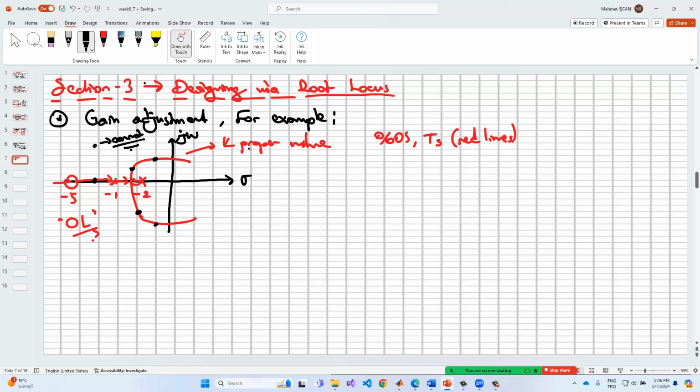But we cannot set this point, because our system cannot permit this selection of these roots, right? Because if we want to set our output response based on the gain adjustment, we use only these red lines in terms of the K values. And so if you want to select the overshoot, settling time, peak time, or the steady state error in here, we need to reach all the poles or the values of these terms.